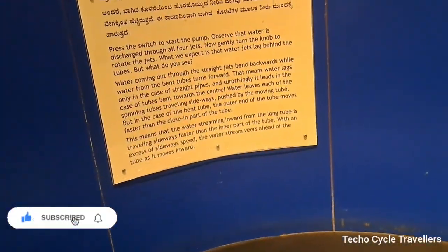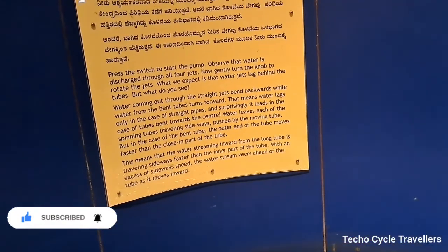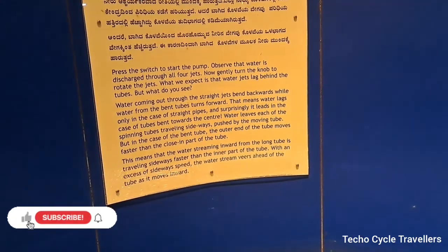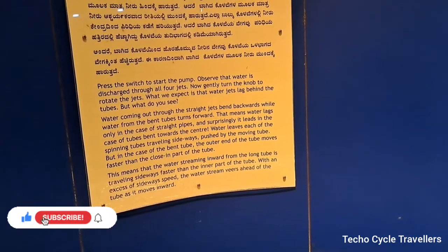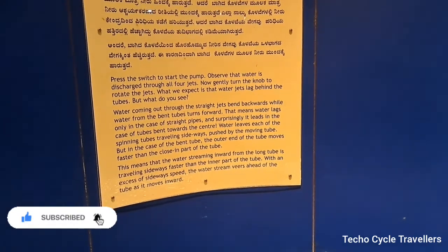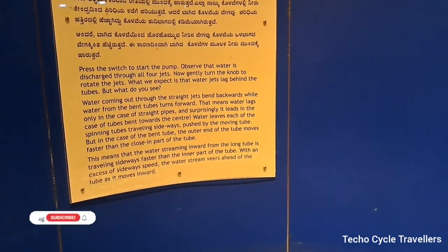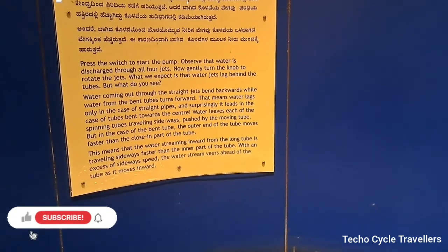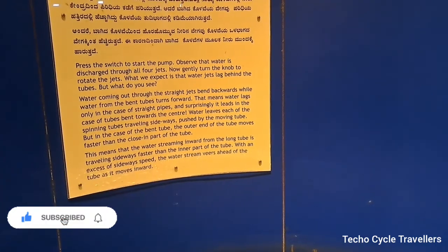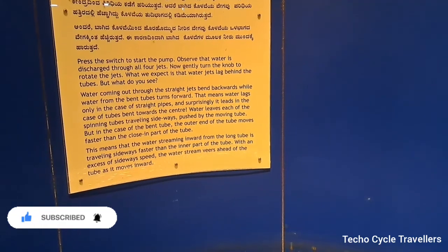Start the pump, so the water is discharged through all four jets. Now gently turn the knob to rotate the jets. What we expect is that the water jet lags behind the tube. But what do you see? Water coming out through the straight jets bends backwards, while water from the bent tubes turns forward. That means water lags only in the case of straight pipes, and surprisingly it leads in the case of tubes